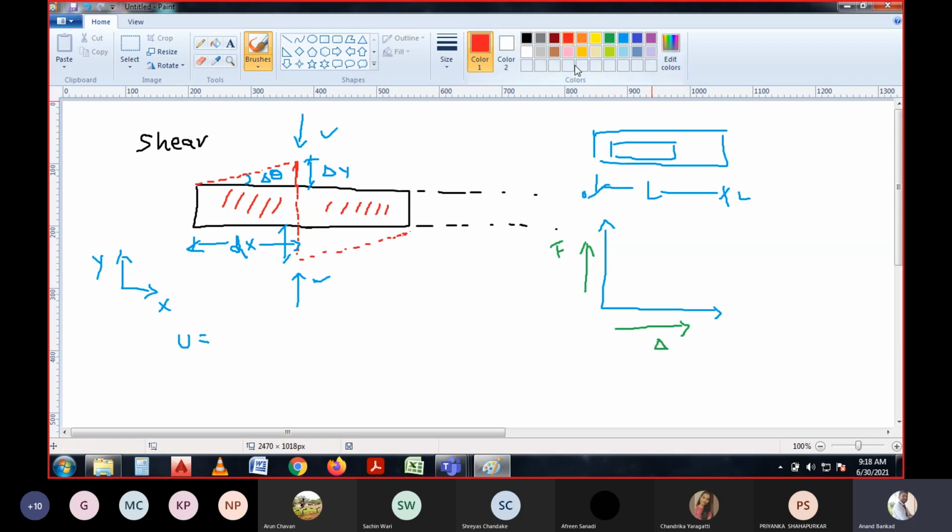So how exactly is this happening? The assumption is that the load is acting gradually. If the load and deflection increase gradually together at any level, that means the load is applied gradually. In the x and y directions, we have considered deflection and load respectively. Once it is considered, the graph will be formed in this manner. If you see the area of this, this is the total load and this is the total deflection.